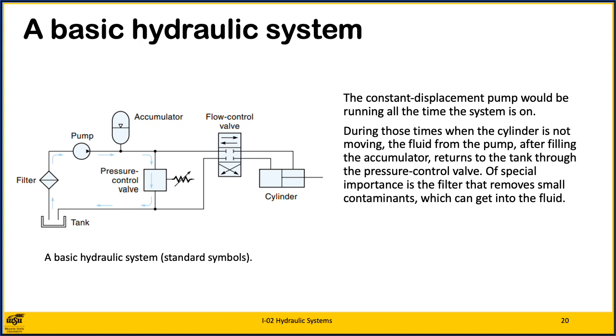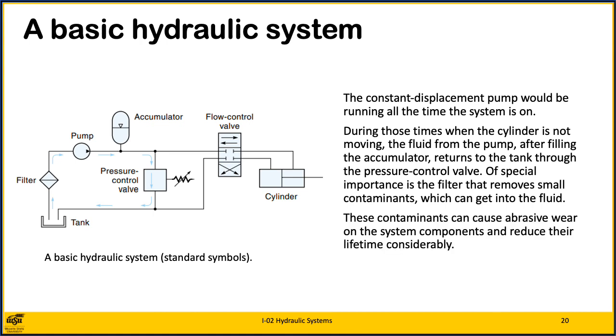Of special importance is the filter that removes small contaminants which get into the fluid. These contaminants can cause abrasive wear on the system components and reduce their lifetime considerably. Of note here is when you use hydraulic systems, keeping the oil clean and dust free is your major endeavor.